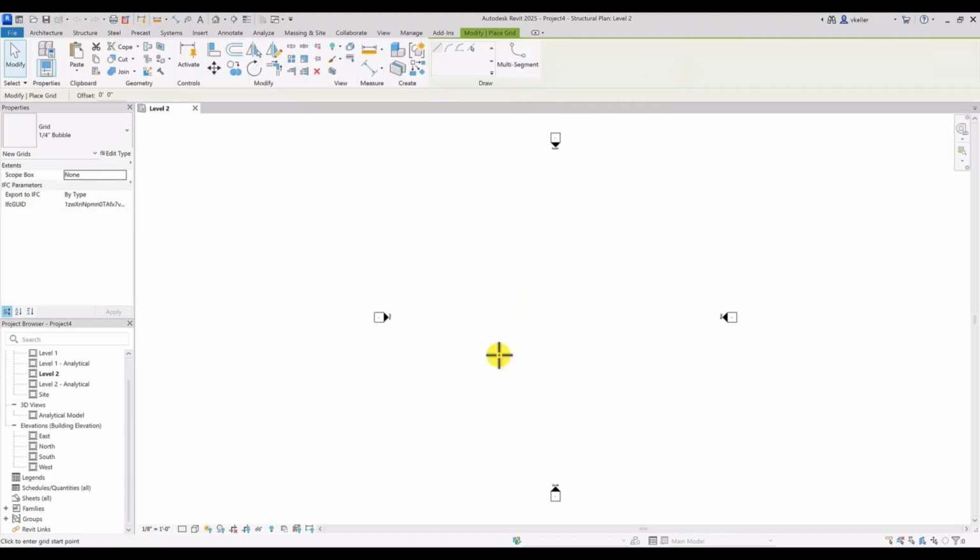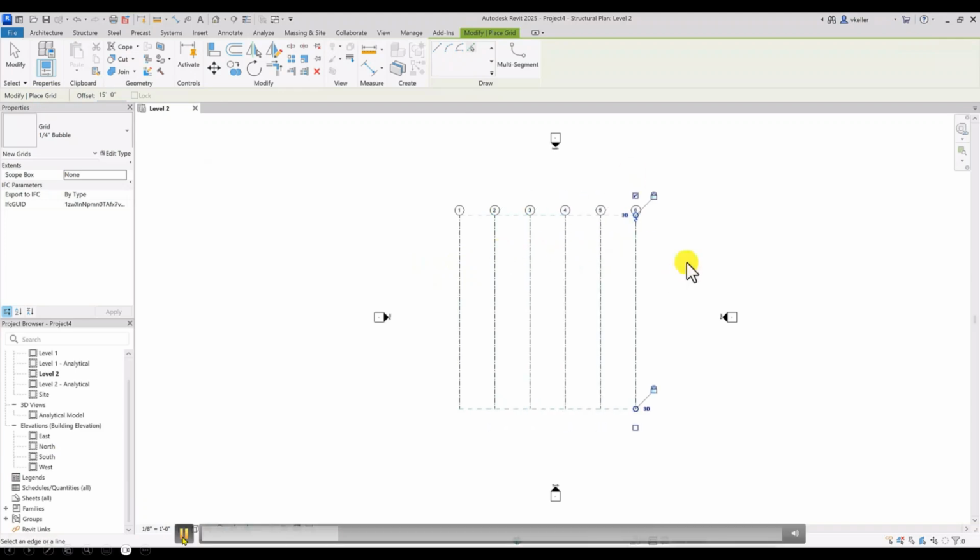If I were to begin, I would start with a grid. But when I do this, it is not groups of grids. It's basically drawing grids one by one. Of course, I can copy and array them to get this done pretty fast. And I have all these cool draw tools. By the way, when you're in Revit, you always look up to the right to see this contextual tab up here. These are draw tools that I can use. Okay, I'm going to let it go.